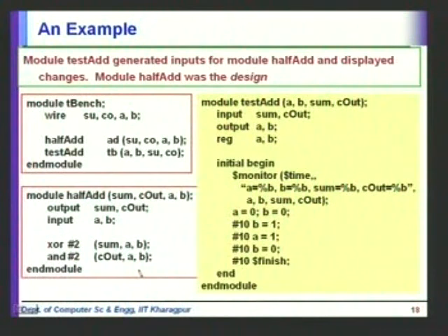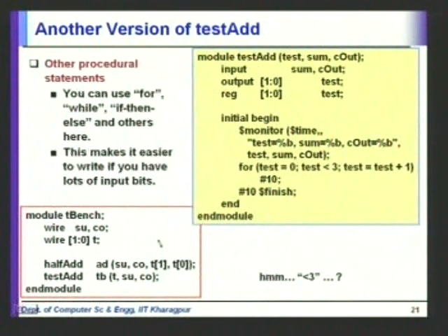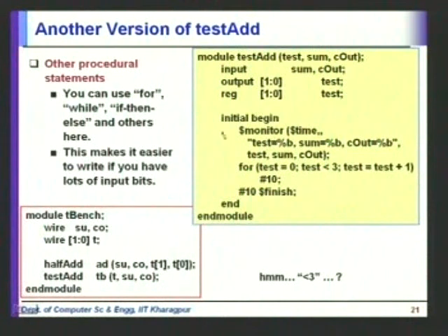All right. Now, because this was written in this way, if we want to use it in a top module which has a multi-bit wire definition, then this is the way we are going to pass them. Very similar to array handling in programming languages. So if you have declared them as 2 separate integers, then you just pass A0 and A1. And rest of this is similar, except that now we have made this slightly different, because now test is a 2-bit word.